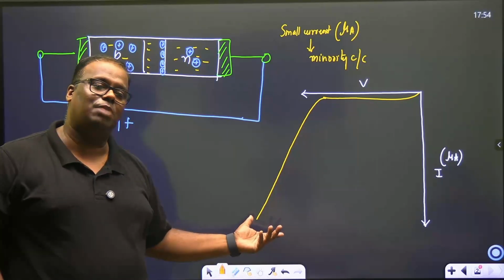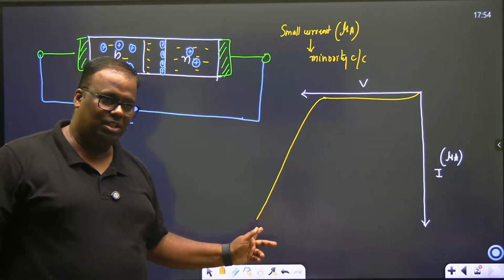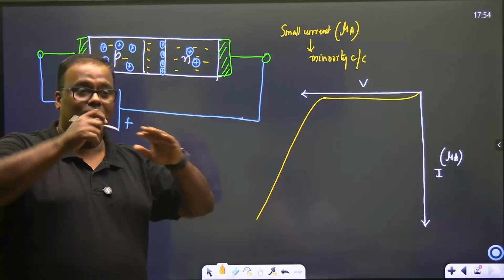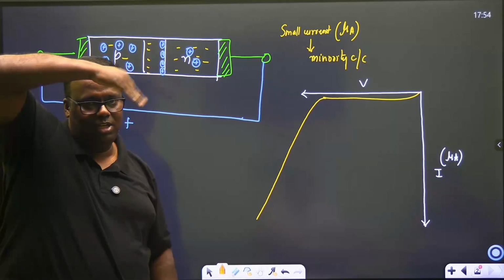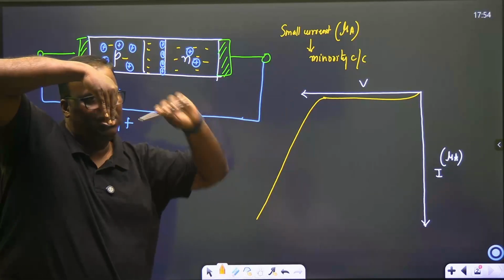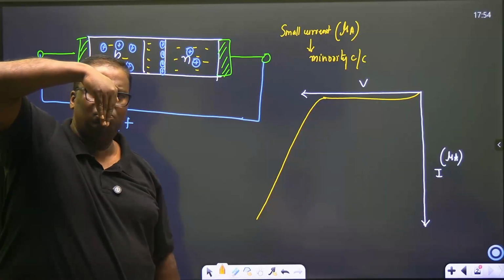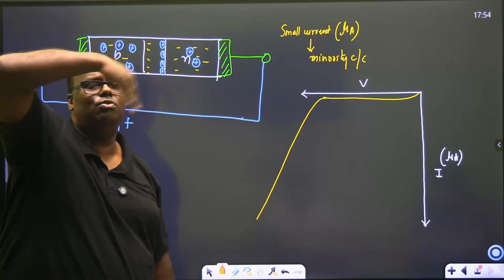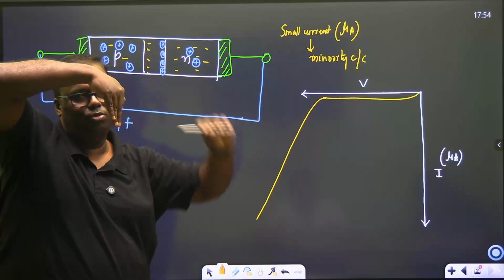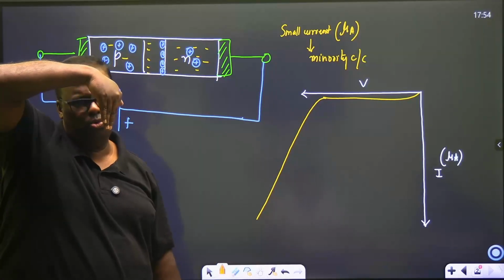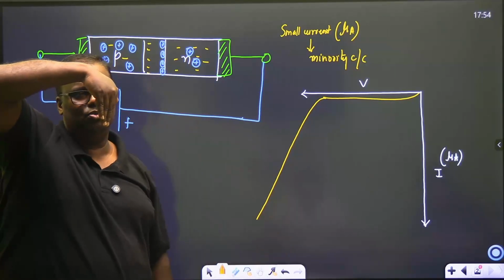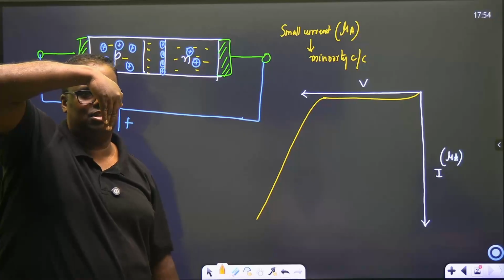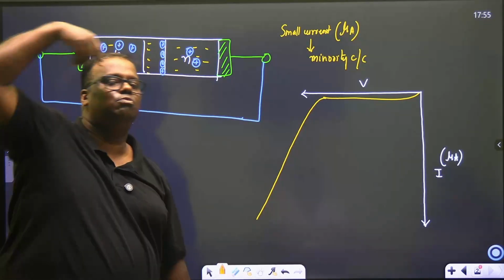You have damaged the product. Did you understand this? This is like, now you made the plate move this side. Now you are pushing water from the other side. The plate will never move because the plate is supposed to move only in one side. Now you're pushing water from this side, so the plate is trying to hold. You are so ruthless. You increased it so much that the plate has now just moved up, and it has moved up forever.